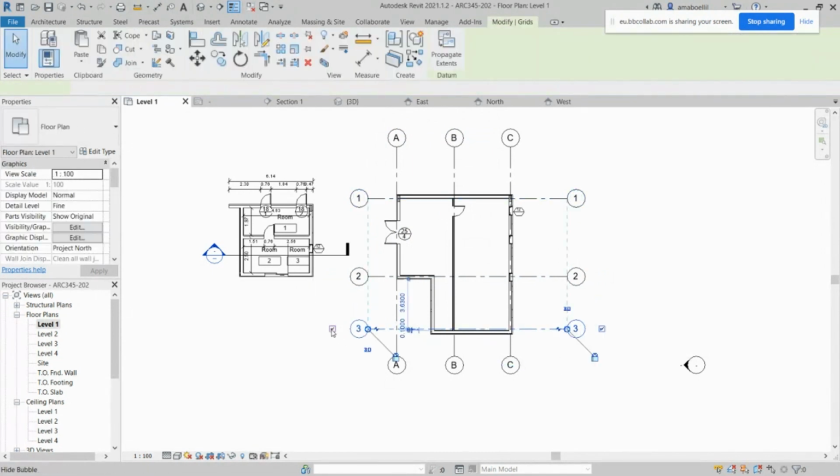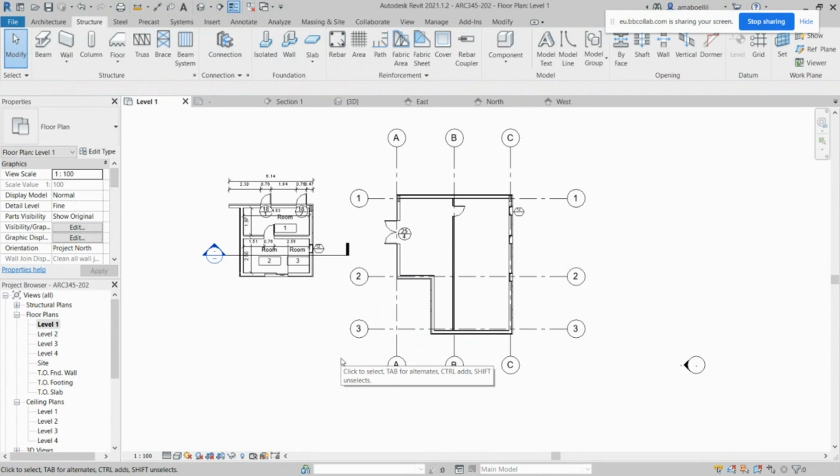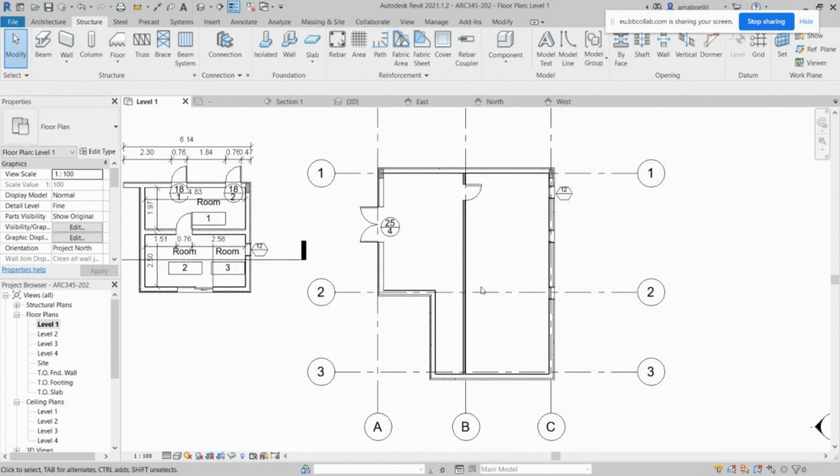So at all of the intersections of columns, we are naming two datums in order to say at intersection B2 we have this column, and at intersection C3 we have this thing, so that we can have coordinates, like the GPS. When you say go to 67 point something east, it gives you coordinates. Here is also a map of coordination in order to relate all of your construction work to these ones.